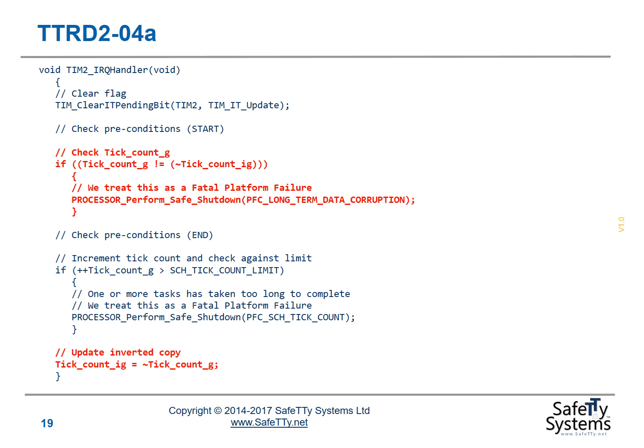And if we detect corruption in this tick count variable, as you would expect by now, we perform a shutdown. We're also continuing the same checks that we carried out before, so we view these as precondition checks. If that variable is corrupted, we don't know what's happening to the system. The only thing we can do here safely, we are assuming, is shut the system down.